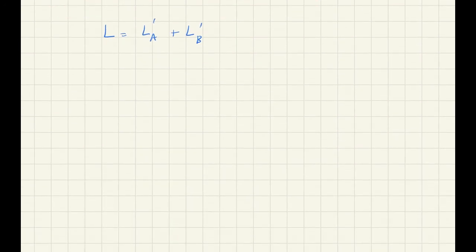So let's define LA prime. That is equal to the sum from j equal to 1 through NV of rho times (Uk plus Uwake, or UW) and (Wk plus WW), dotted with the tangent vector in the wing fixed frame.